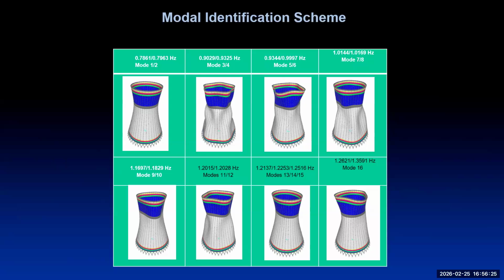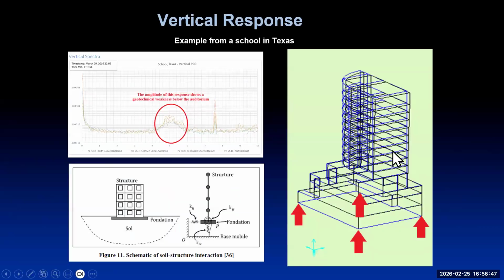It's an amazing project, but little by little, you could see all of these frequencies tighten up and get much more stable. And when you did an analysis in the finite element model, you would see that under a 100-mile-an-hour wind, you started with like 2 feet of deflection and it worked its way down to about 4 inches. And it was a very clear example of how the actual construction was actually improving the quality of the structure. So anyway, it was a great example.